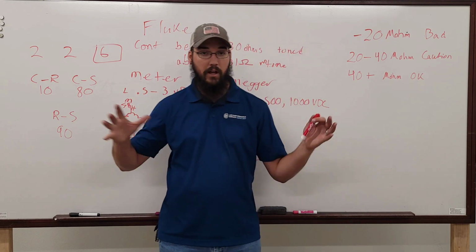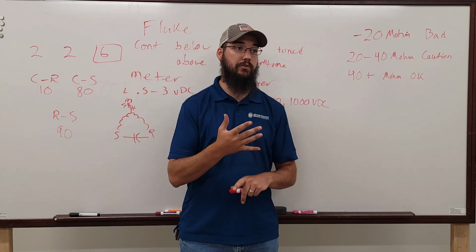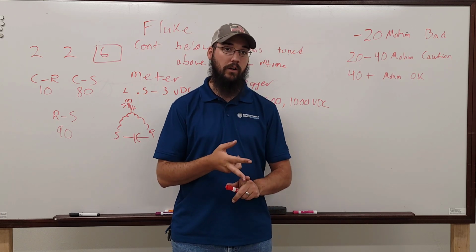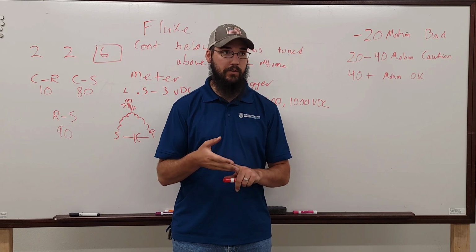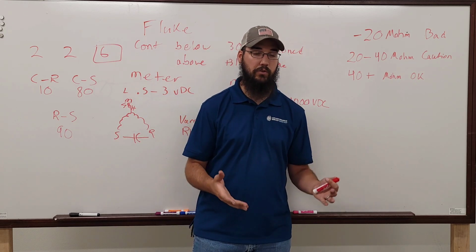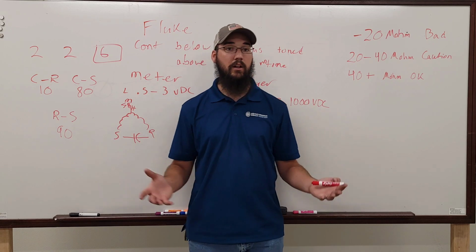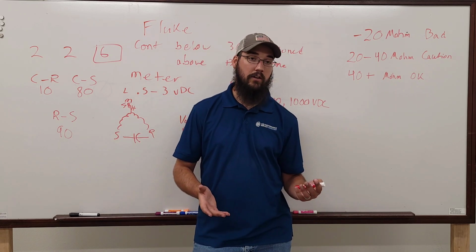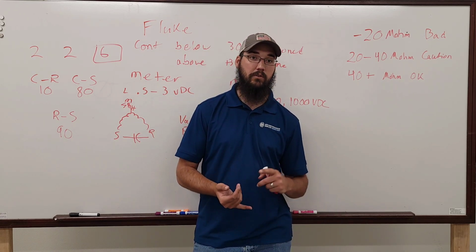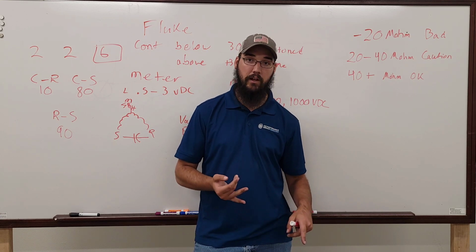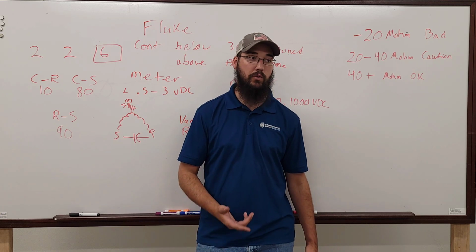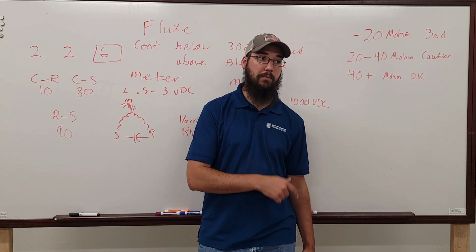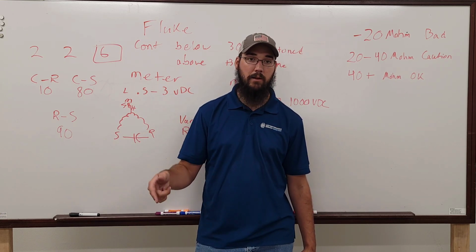And that applies to both scenarios, whether it's belt driven, direct drive, or pumps. It's got a coupling. That same principle applies to each of those scenarios. But if everything else checks out perfectly fine, you've got horrible bearing readings, but there's no noise, there's no play, the motor's running fine, but all the readings are just crazy. Be cautious of the bearings and look more at the alignment and mounting.